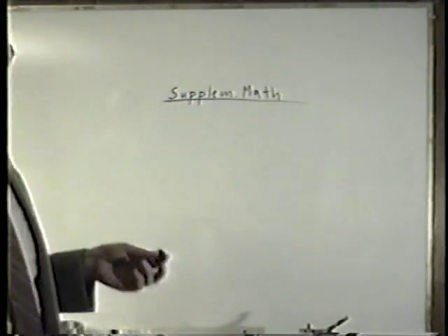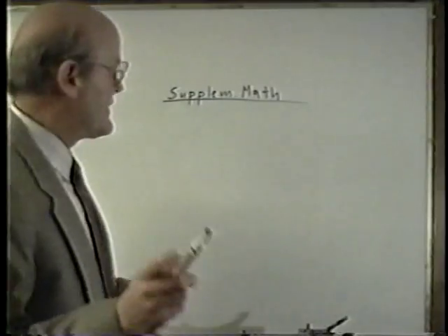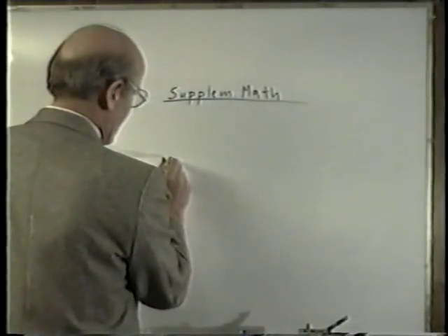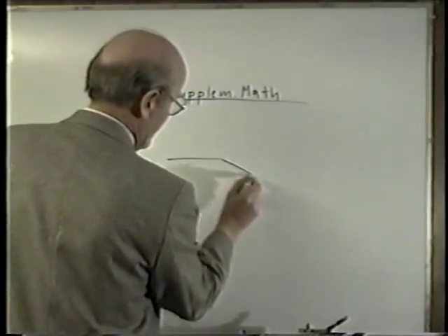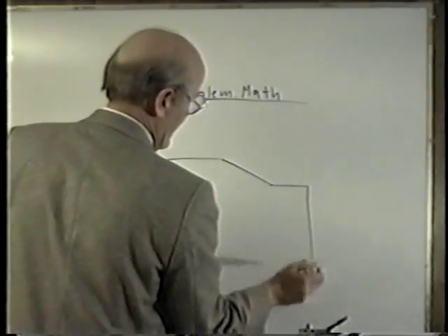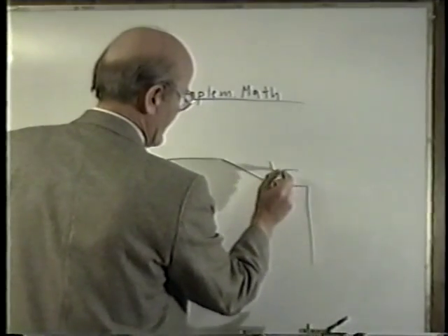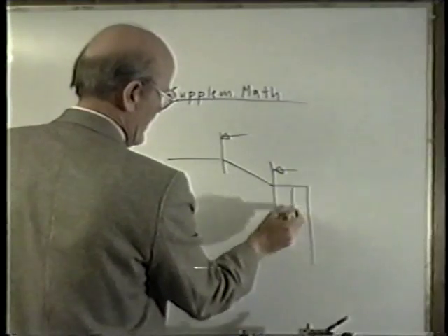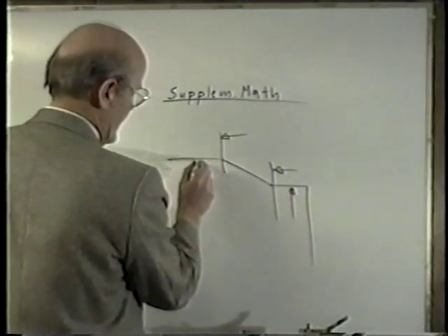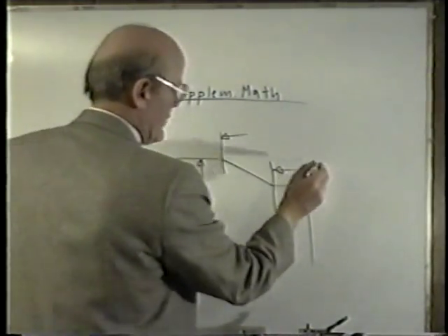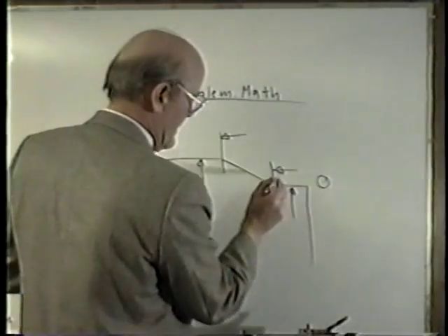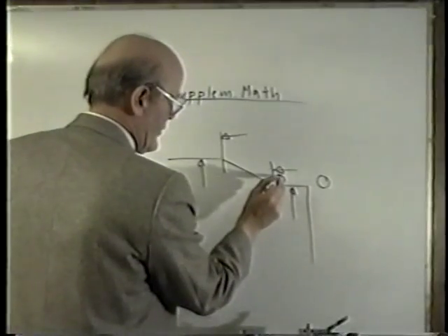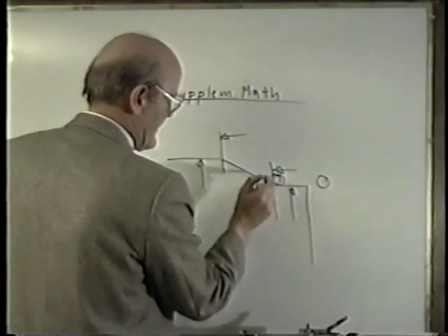Let's assume we have a machine tool that does not have the feature of nose radius compensation. Nose radius compensation in the lathe would mean that when we program a shape that looks like this, we program the actual intersection points. We program this, and we program this dimension and this dimension right here. And our tool will go from here, not to here, but the control itself will have the ability to put a tangent to this.